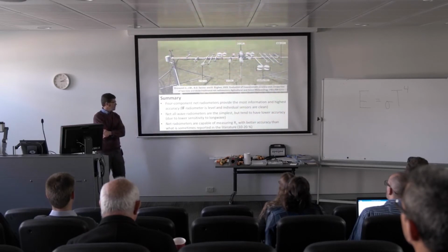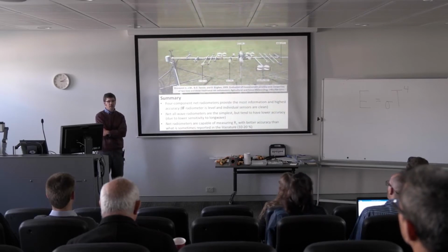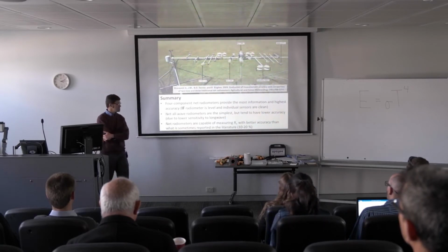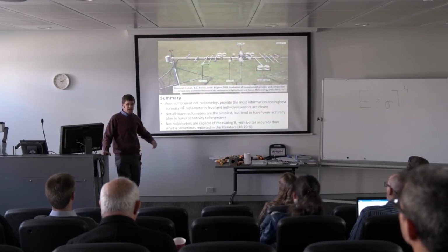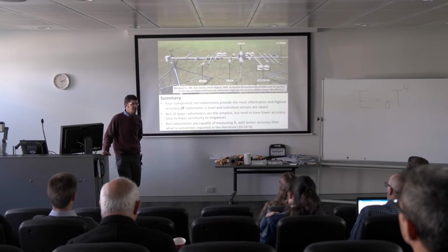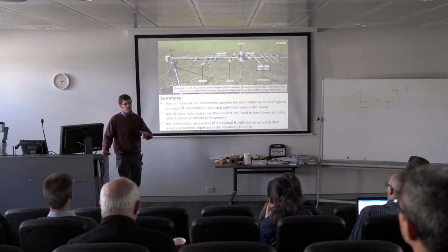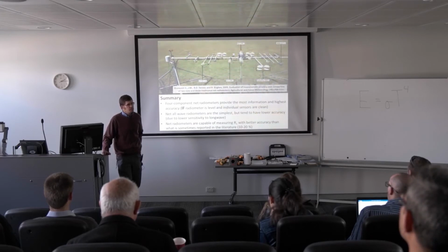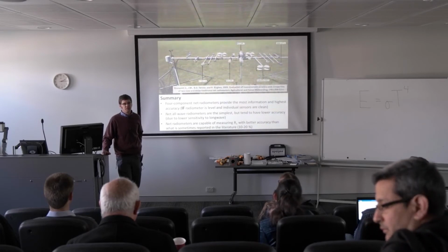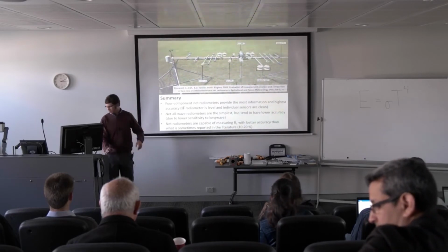We found that net radiometers were capable of measuring net radiation with better accuracy than what's often reported in the literature. There's quite a few studies out there, like energy balance studies, especially at flux tower sites, that indicate net radiation uncertainty is like 10 or 20%. I think if you're measuring it with a 4-component net radiometer that's well leveled and clean, then the uncertainty is probably lower than what's usually reported in the literature for net radiation measurements.